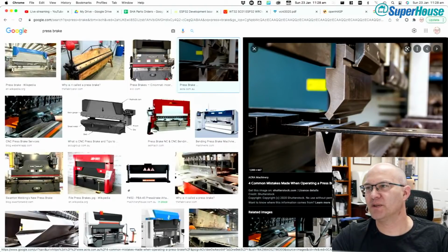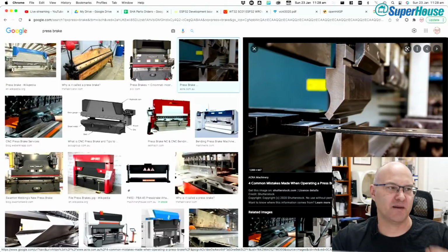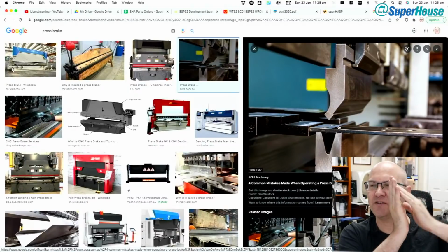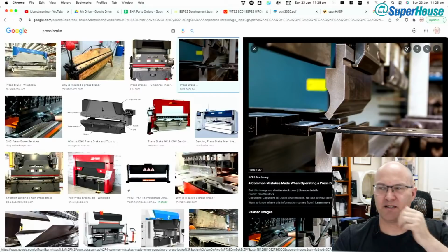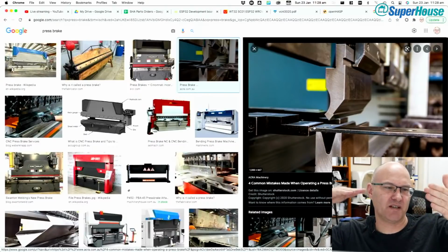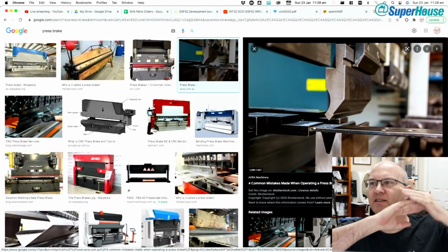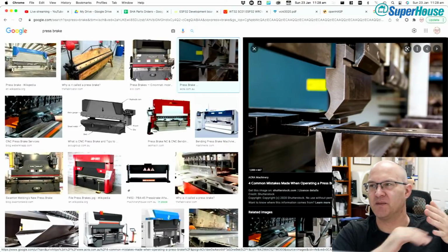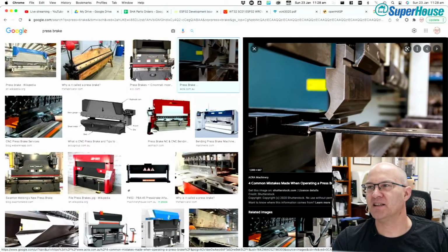Now, usually when you do that, you want that bend to occur at a very precise location. It needs to be the same every time, so that when you're taking a piece of metal and bending it into a shape, you don't have that bend occurring at a different location. The way that is done is by setting the depth using this piece at the back, this block of metal which stops the workpiece from going any further back. You butt it against it, and then you know that it is at the set position. So the depth guide, this backstop, is adjustable.